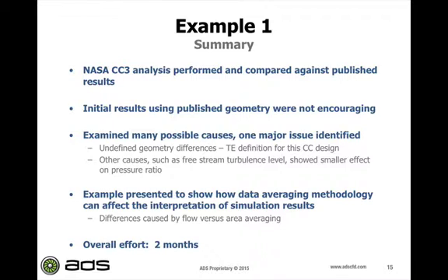But we find the major issue in our simulation not matching the data is we did not capture the trailing edge shape for this design, so we miss a lot when we compare against experimental data. Other causes such as free stream turbulence and surface roughness do not have such a strong impact on this geometry as the true trailing edge geometry.